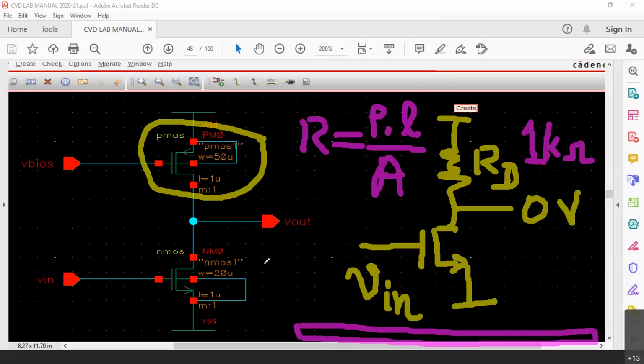So whenever such constraints are there, the IC manufacturers, what they do is, if at all there is a larger value of capacitor required inside the chip, they cannot have a larger value capacitor. You cannot have a 1 microfarad capacitor inside the chip. For that matter, manufacturing a nanofarad capacitor inside the chip is also expensive, area wise, because you know that C is equal to epsilon A by D, where value of capacitance is directly proportional to the area.